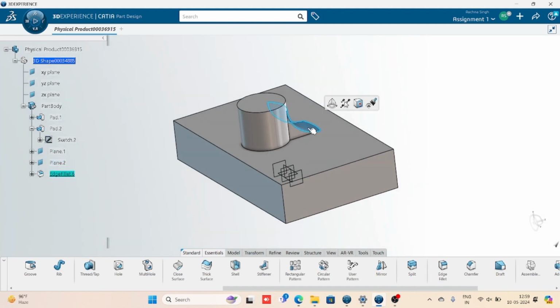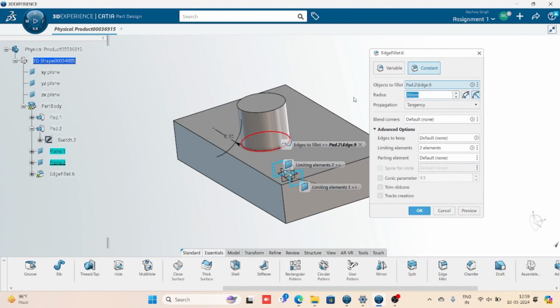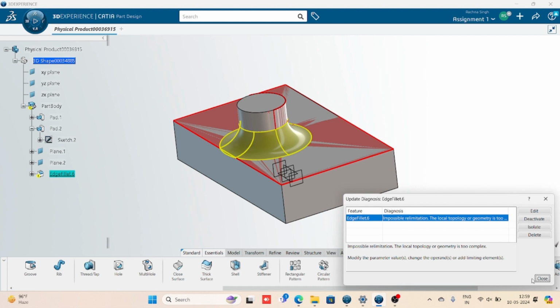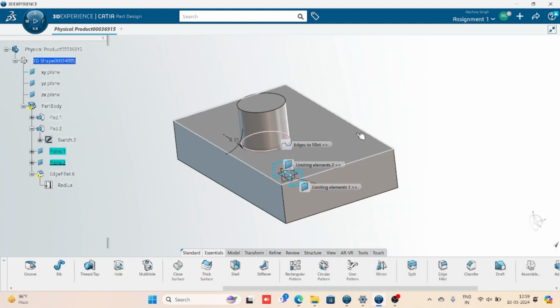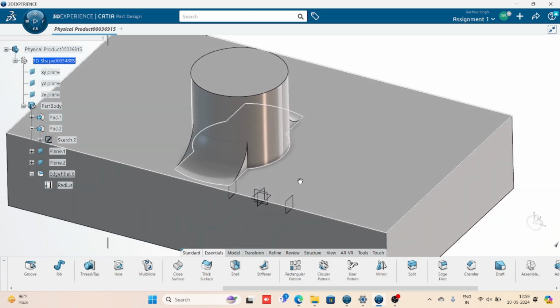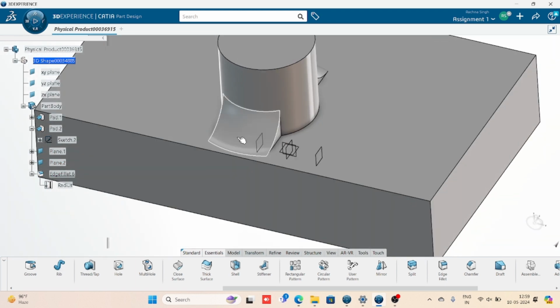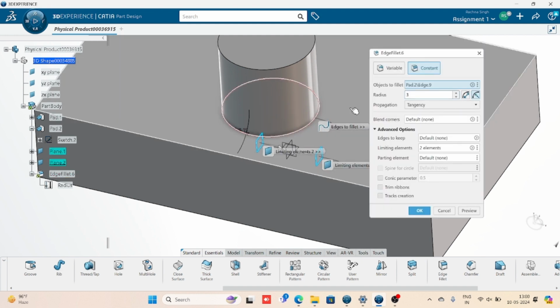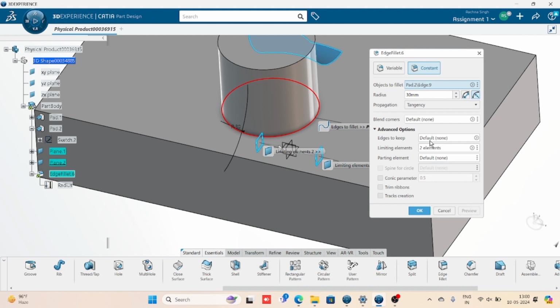Okay, I'll reduce the fillet radius, then you can see it on both the sides. It's showing some numbers, just hold a minute. Fine. Because the edge was disturbed, that is the reason. If I want to give it 30, then I should define keep edges, and only then will it show on both the edges. You can see.